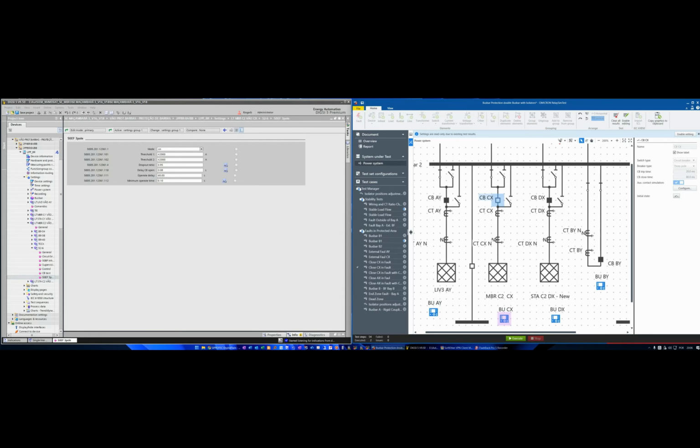So the signal of close command, manual or auto reclose, is important to be put in the signal of the protection. Why? Because you take the signal and you put it like this: please, bus bar protection, see this current when you do a close command or when you do an automatic reclose. So in this example that I give to you, I will have a fault.